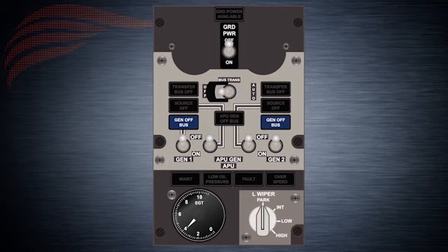AC transfer bus 1 is isolated from the AC transfer bus 2 if only one IDG is supplying AC power to both buses. DC buses are isolated from each other. If there is no manually active AC power source to the related transfer bus, a source off light illuminates. Similarly, if an entire AC transfer bus is not powered, the related transfer bus off light illuminates.